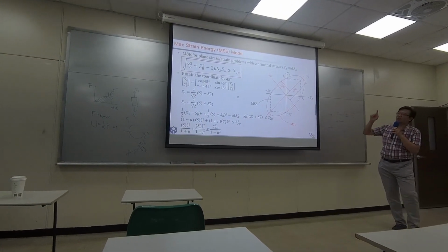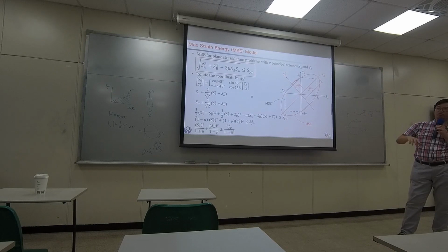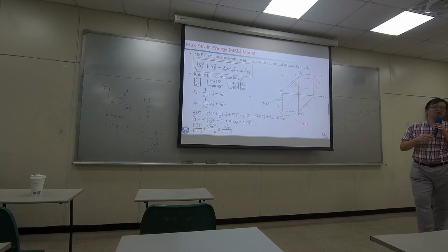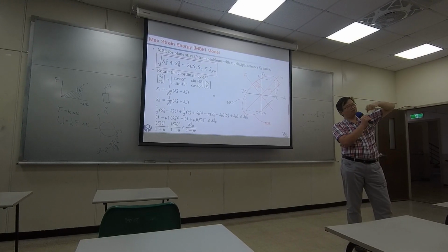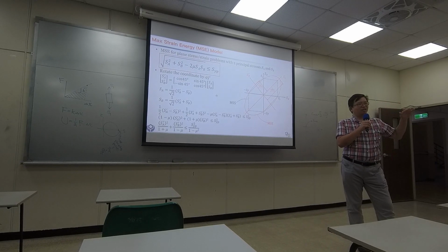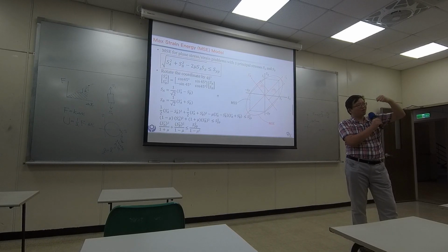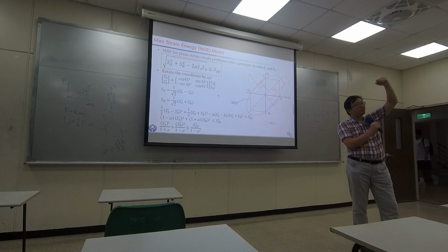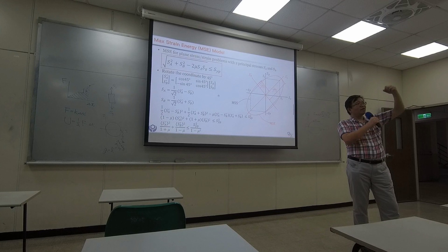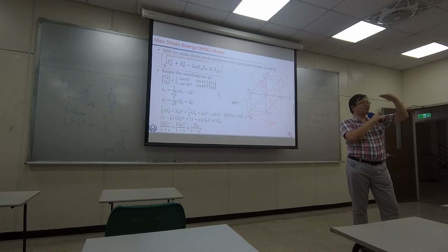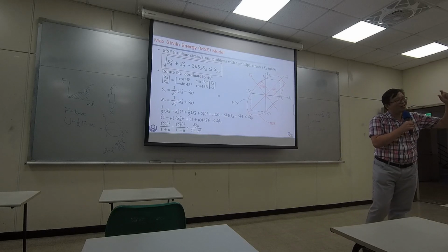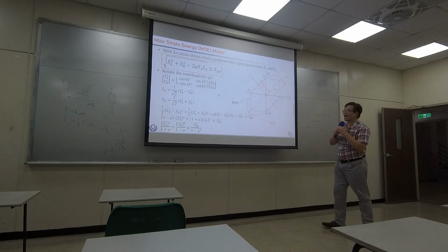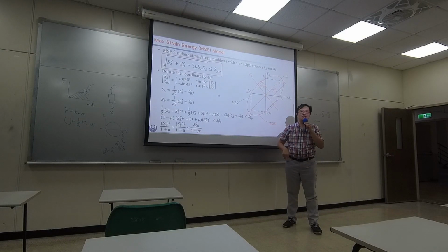However, in the maximum strain energy model, we introduce one more concept, which is Hooke's law. In Hooke's law, when we pull the material along the up and down direction, we care about how the stresses along different directions affect the deformation. So when we pull up, reaching some limit, and when we pull left and right, it actually shrinks the up and down direction a little bit. So it seems like it allows you to pull up and down a little bit more. So Hooke's law allows you to do a little bit more.